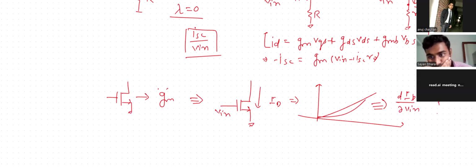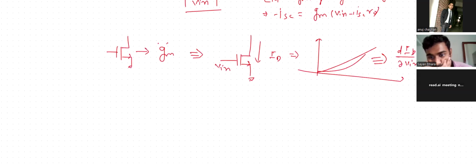This is the definition: when you plot the current for different V in, keeping VD at some potential, some VDS, let's say VDS of 1 volt, we draw ID versus V in and take the differentiation of that curve, and we get the GM. This is the mathematical definition.